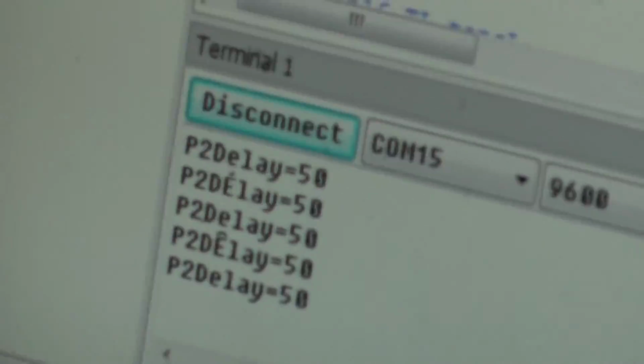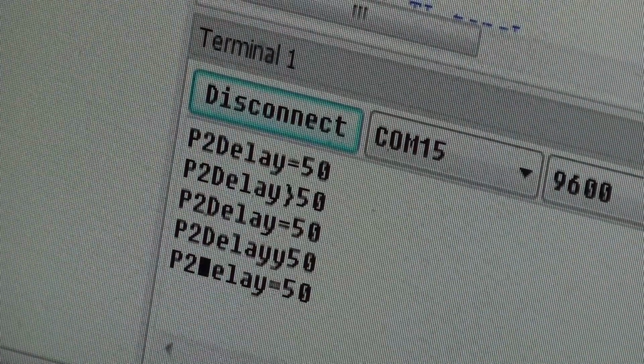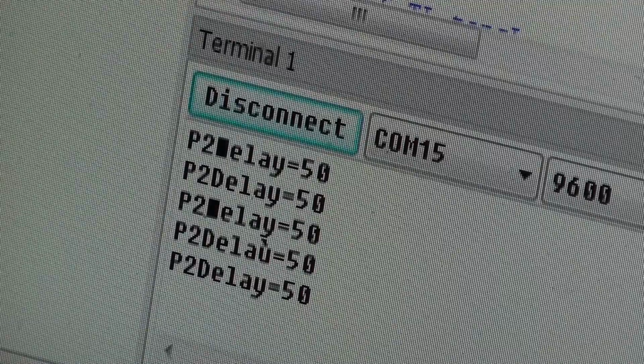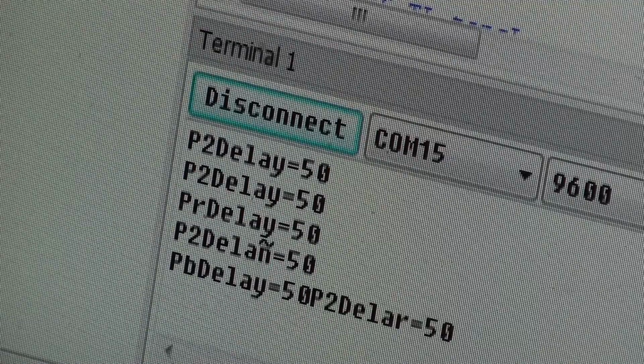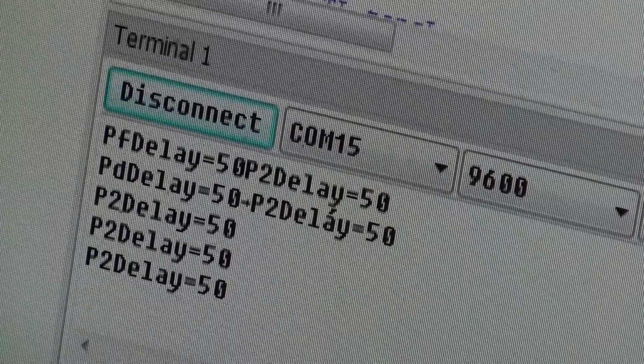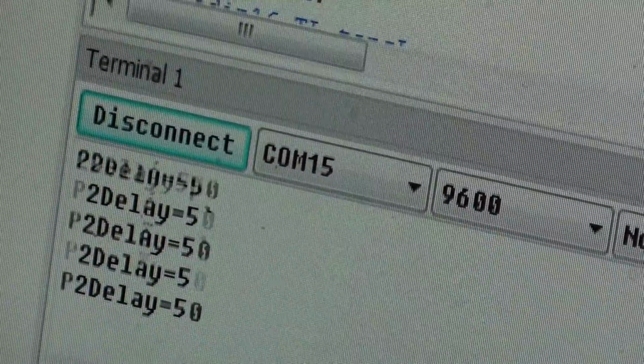You're just getting the odd character coming out incorrect there, and that's because the interrupt plus the delay occurring in there is starting to interfere with the serial communication, so it's actually getting framing errors. And on the logic analyzer, if I go into that and refresh again, you can now see that we're running at 100 Hz at the top, and we've got exactly 50.06 microseconds on the output again.